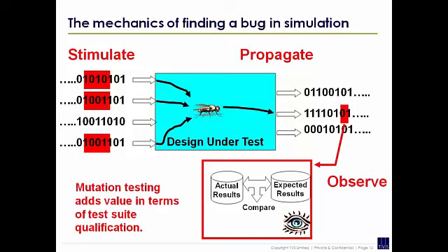The one thing that does it now is something called mutation analysis. Again, it's quite an expensive technique. It works at the end of your verification process, when the verification engineer says, right, we've done it, we're confident. We've got 100% MCDC. We've done all the stimulus, all our requirements are tested. We've done all the tracking. We've validated our test bench. We think everything's done, we're signing this verification off. This design is ready to go into the airplane.